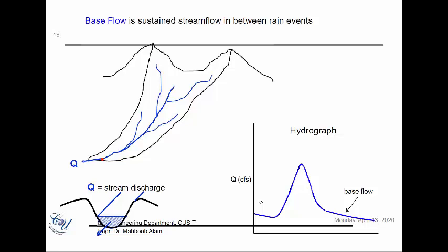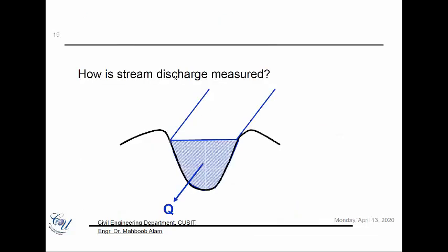At this level, at undergraduate level, it is enough to understand that there is a thing called hydrograph. Hydrograph is a kind of time series of discharge with the x-axis containing time and the y-axis containing the discharge, and that there are different parts of the hydrograph which are associated with the different processes that are occurring in the catchment. Now, how do we measure discharge?